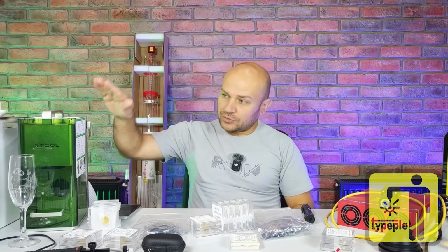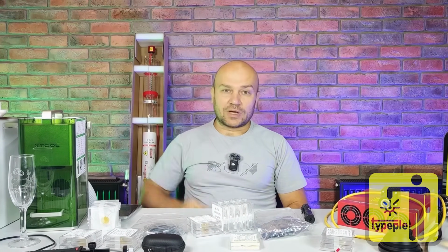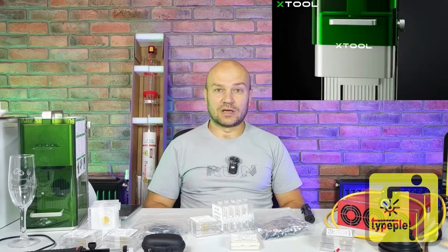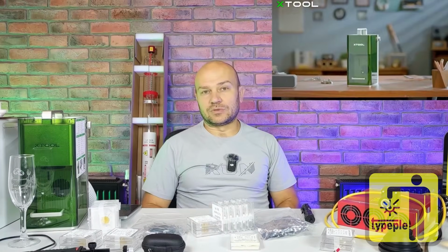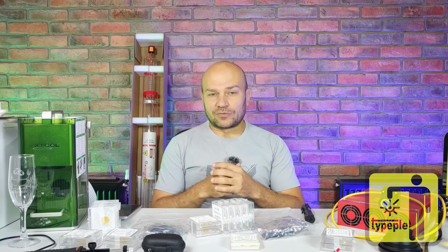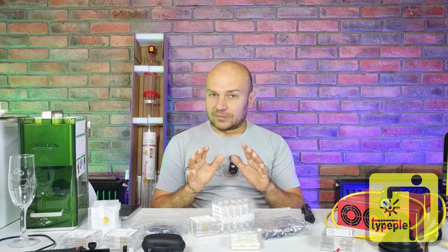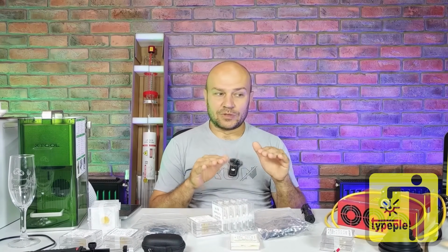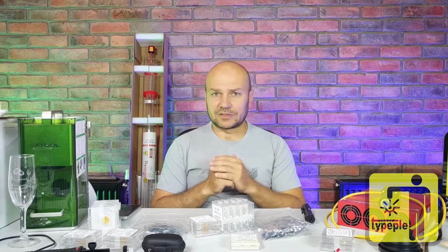We have a similar machine from Xtool, the F1, which is a diode-based marker. It uses two types of diodes, a 450 nanometer blue diode and a 1064 nanometer diode. The latter is an infrared diode, used for engraving and marking metals. Each diode and laser requires a specific type of lens, with its own lifespan, parameters, and so on.